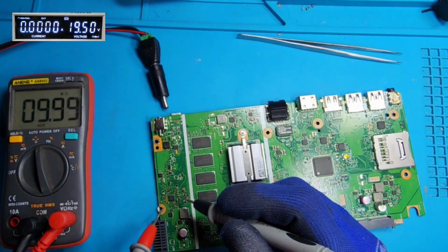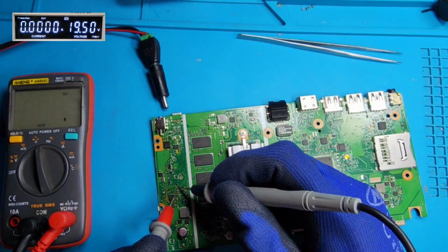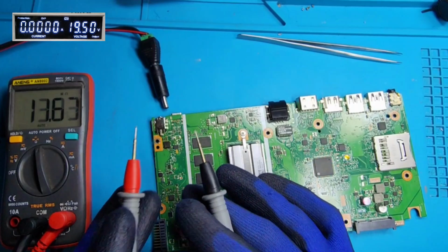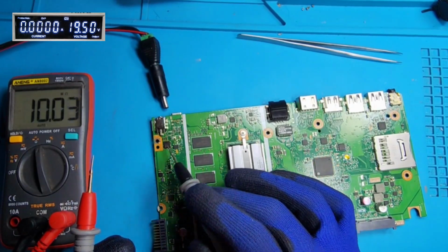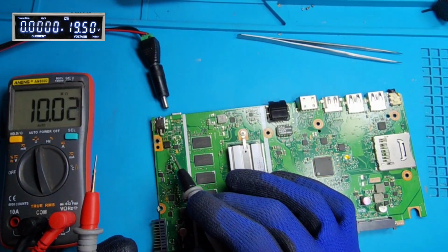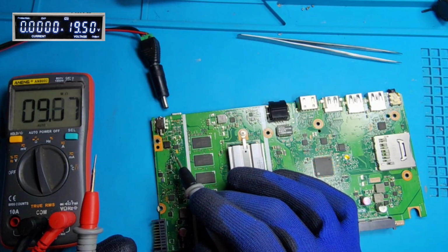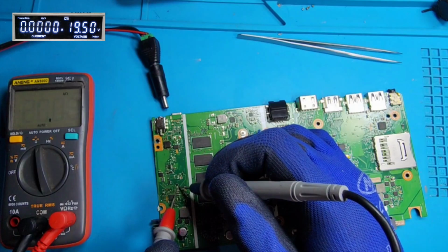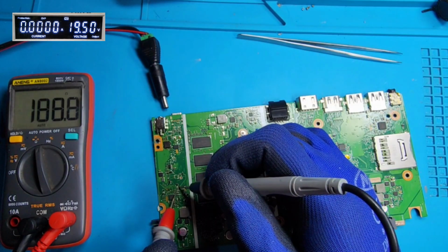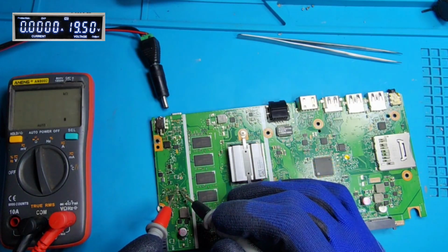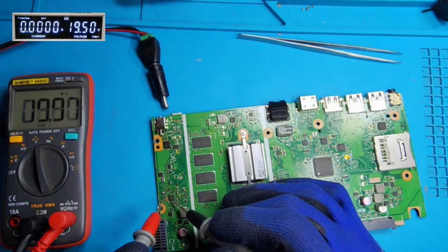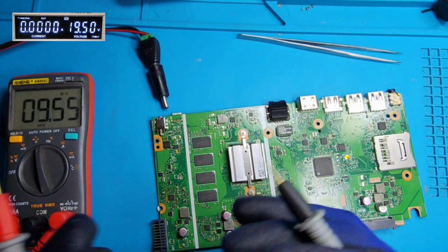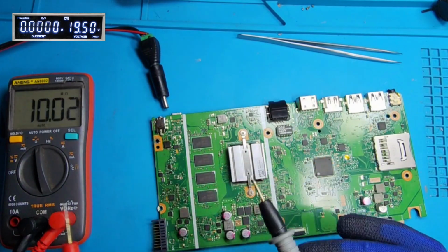So that's why the charger IC is not getting enough current to produce the charge pump voltage for the MOSFETs here. So these two are internal MOSFETs. They need to have 25 volts at the gate point. And here we have 188 ohms. So as this resistance increased, the current for the charger IC will be reduced. So it will lose the capability to produce the charge pump voltage of 25 volts.